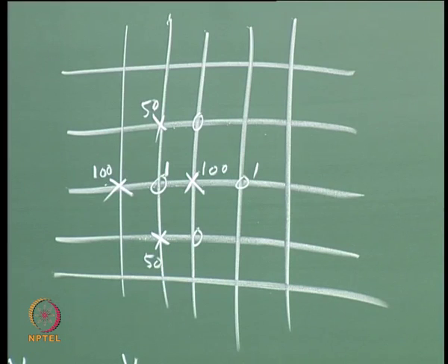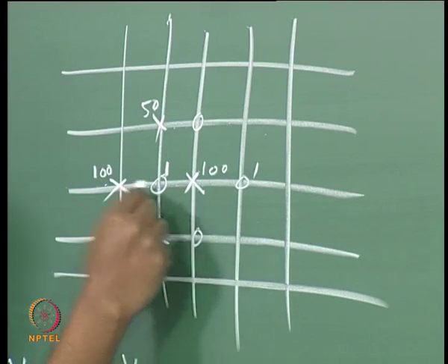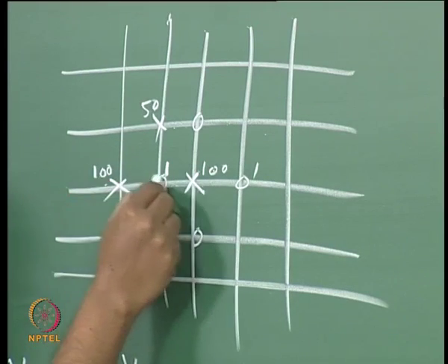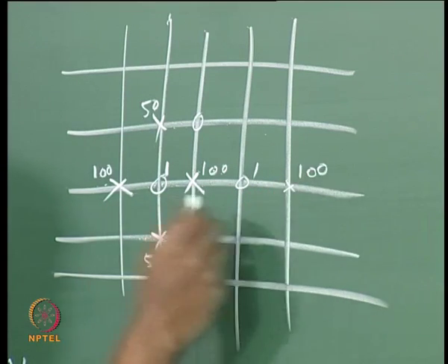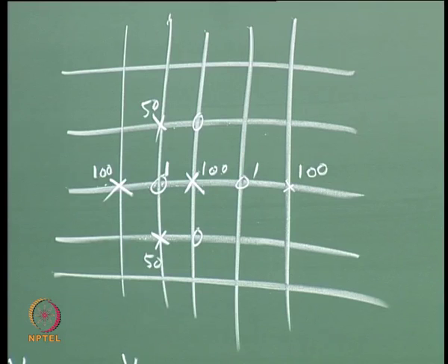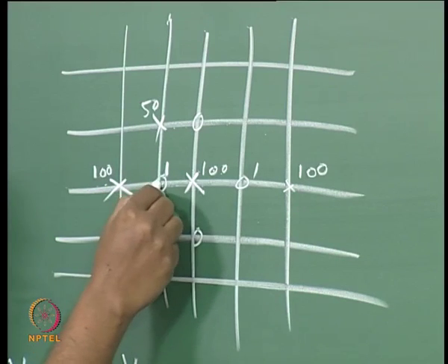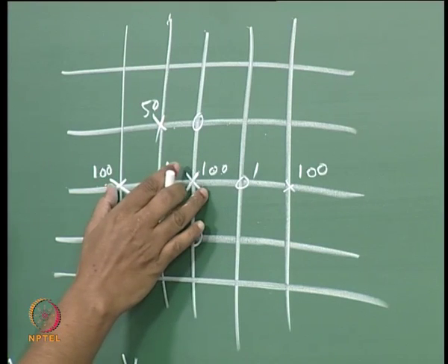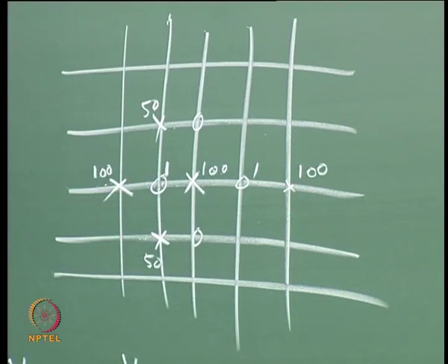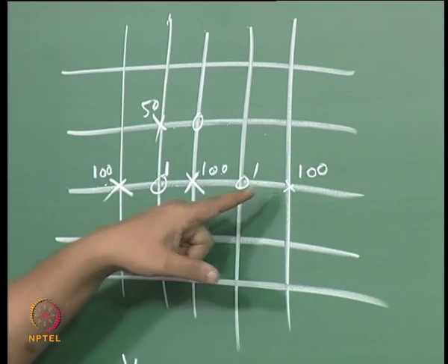So in that sense one can come up with a pressure variation like this, which is strongly varying between 101, 101, 101 like this, which is seen by the flow as if it is a uniform pressure, because the pressure gradient is being determined by 2 points by skipping this particular point, and this is 100 and this is 100, so it is uniform, so the flow will not react to the fact that you have these very rapid variations of pressure.